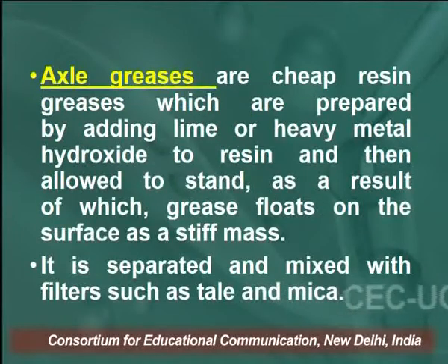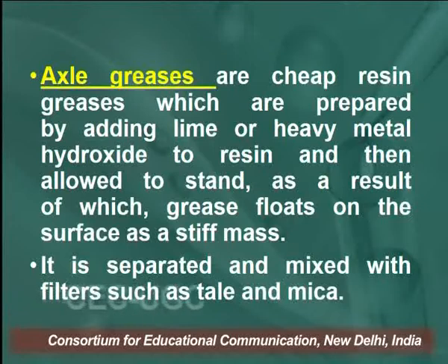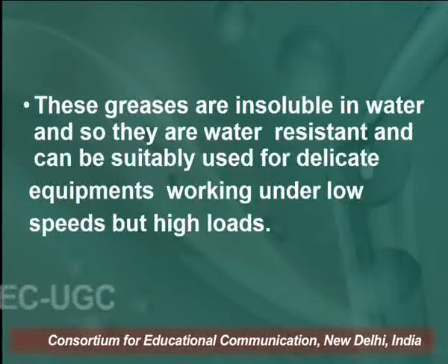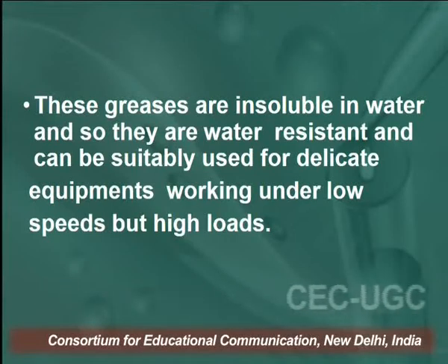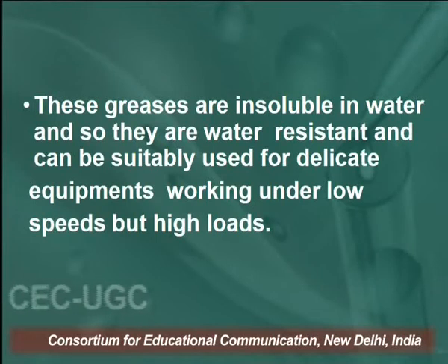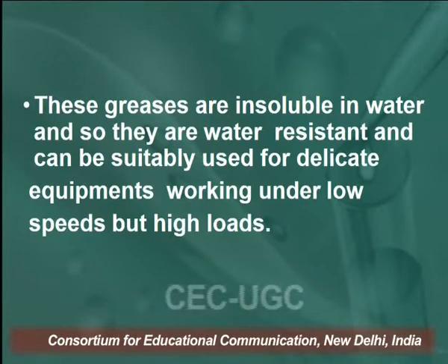Axle greases are cheap resin greases which are prepared by adding lime or heavy metal hydroxide to resin and then allowed to stand, as a result of which grease floats on the surface as a stiff mass. It is separated and mixed with fillers such as talc and mica. These greases are insoluble in water and so they are also water resistant and can be suitably used for delicate equipment working under low speeds but high loads.